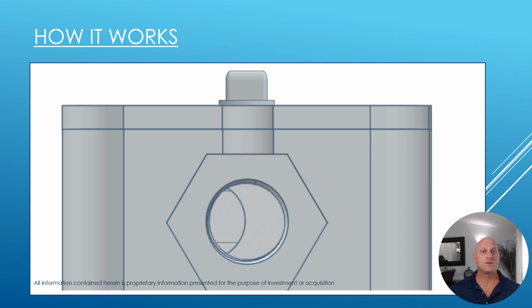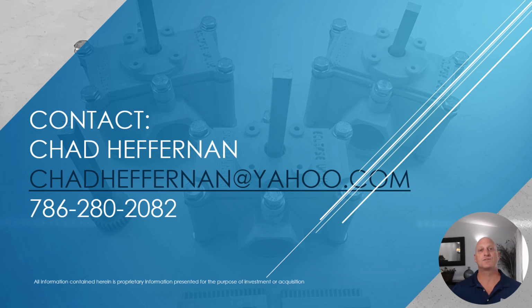The end result is that we have a very equal percentage type of flow, and it's very easy and precise to control your flow just like a globe valve, but it's full bore like a ball valve. It's also quarter turn like a ball valve. It is also inline serviceable, so it's got 6 bolts that can be rebuilt in just a simple matter of a minute. 3 moving parts, very simple, inexpensive to manufacture, and should be able to replace any kind of flow control device out there, as it is superior to all of those designs.